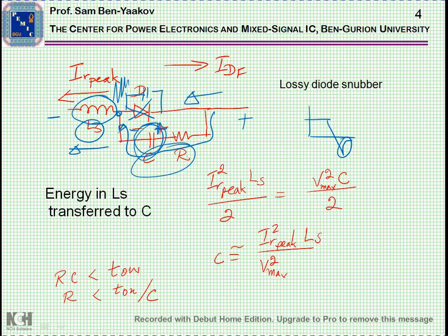Now, once the circuit is switching to the other state, current will start flowing this direction, the diode will conduct, and consequently the RC circuit has now a path to discharge this way, and get back to the zero condition.